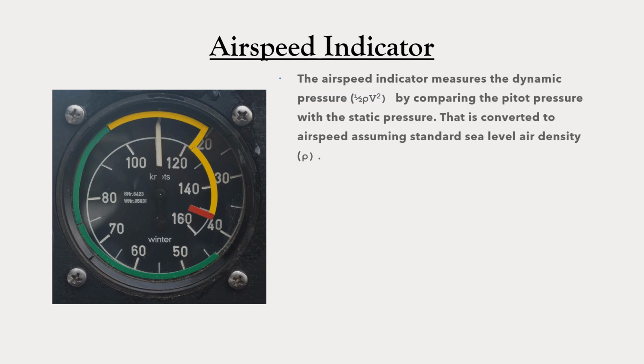So the next pitot-static instrument is the airspeed indicator. The airspeed indicator uses both the pitot pressure and the static pressure. In fact, what it really looks at is the difference between the two.